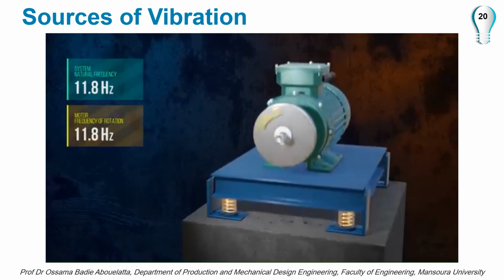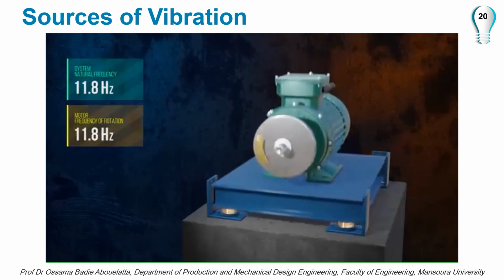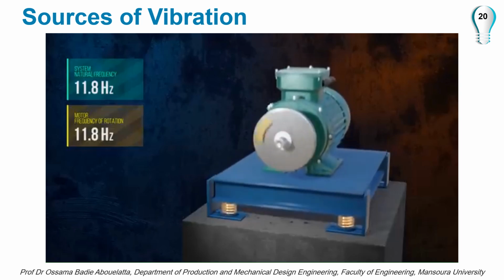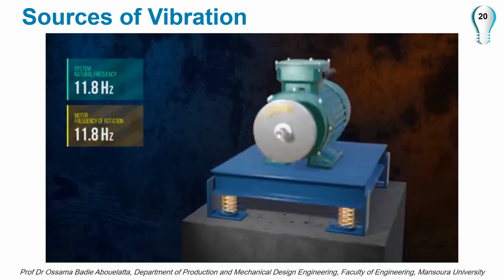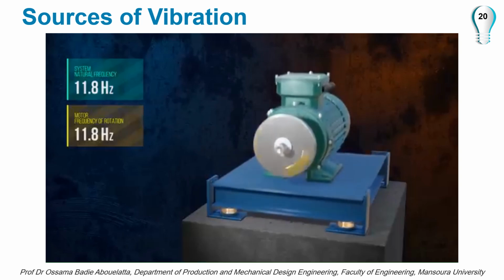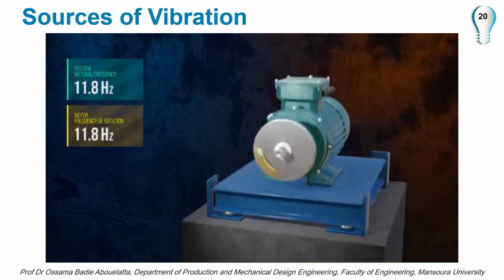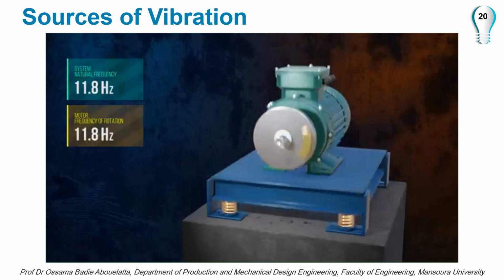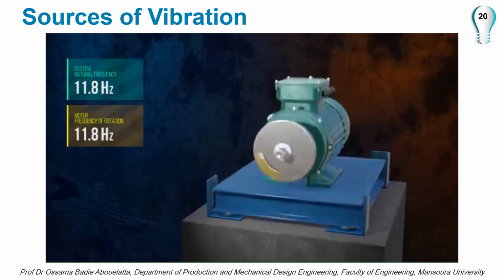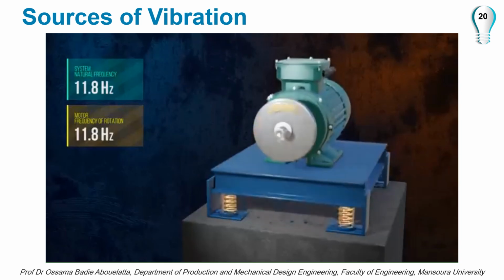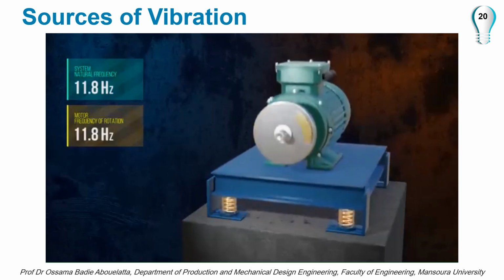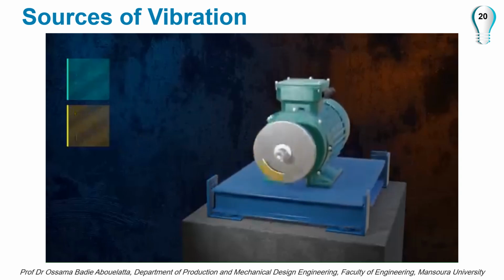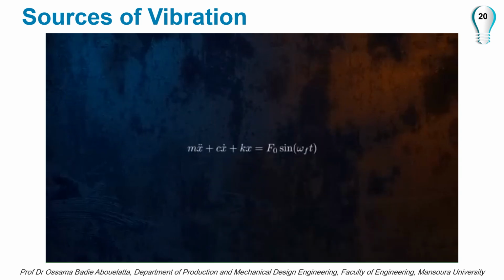It's one of the reasons it's so important to be able to calculate the natural frequency of a system. If the natural frequency of a bridge matches the frequency of wind loading acting on it, or of pedestrians crossing it, the results can be catastrophic, particularly if the structure has little damping. Devices called tuned mass dampers are sometimes installed in buildings and bridges to control the dynamic response at resonant frequencies. With a rotating eccentric mass, the external force acting on the system is a simple sine wave function.